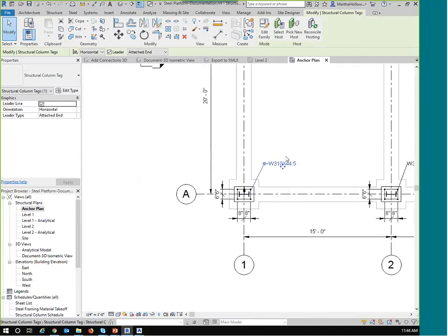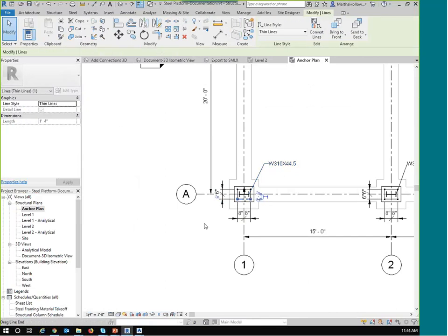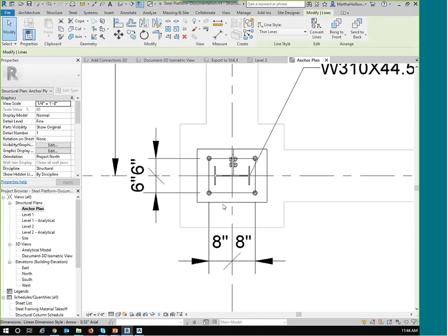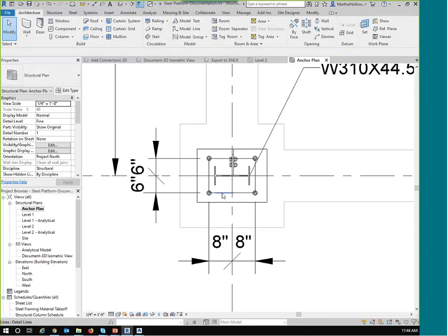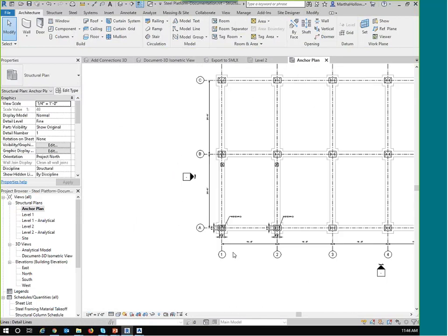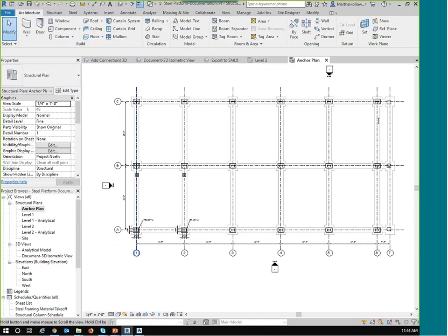And in some cases, like the holes, I wanted to do the holes. Revit dimensions don't acknowledge those holes existed, so I had to draw detail lines. That's what those little things in there are. I added detail lines so I could actually dimension my holes. So very limited fabrication documentation tools, nothing to go to the full fabrication things. You can't send it directly to the fabrication equipment of any kind.